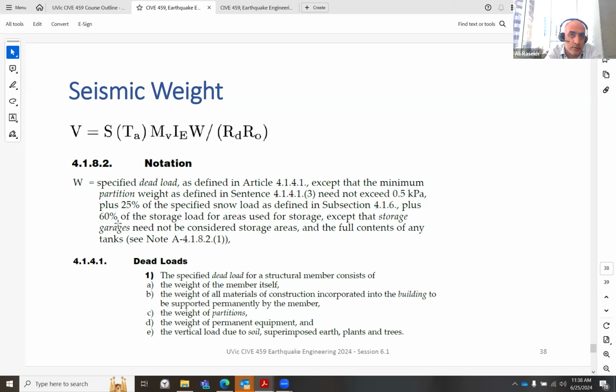And in Vancouver or Victoria is less of a concern. A storage load appears to be almost permanent, although it might not be categorized as dead load, but it's almost permanent. So I tried to give a good estimate of what loads in the building will really experience that earthquake, which is like, what was it, like 2,500? So 2% probability every 50 years. 50 years is like maybe the expected life of a building or a structure.